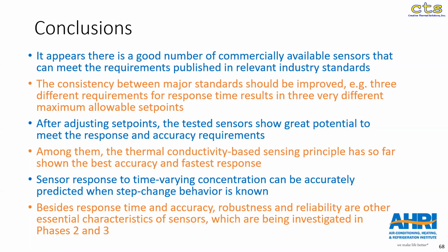inhomogeneous results. However, after adjusting the set points, we were able to demonstrate that the sensors we evaluated had great potential. They met the response time and accuracy requirements, so there was no concern from that, but it required a little bit of tweaking and really adjusting these set points. That's a very important point. What we've also seen is, among the sensing principles tested, and this is not to endorse any of the technologies, but just an observation, that the thermoconductivity-based sensing principles so far have shown good accuracy, highest accuracy, and also fastest responses.